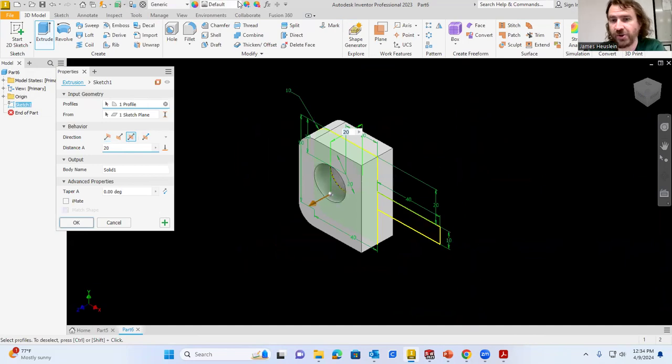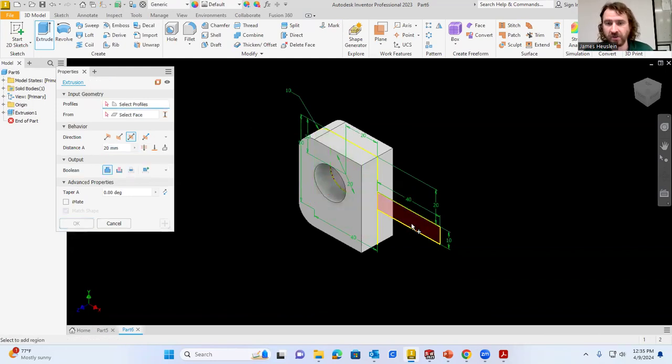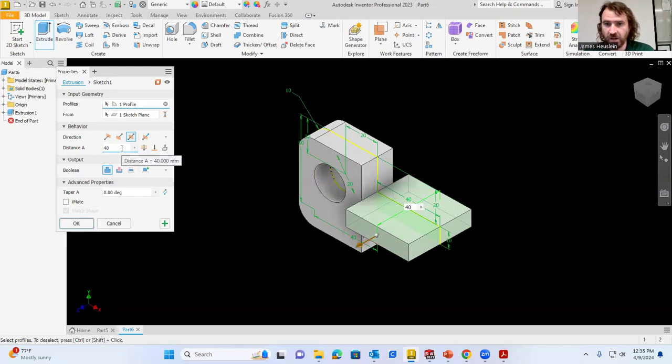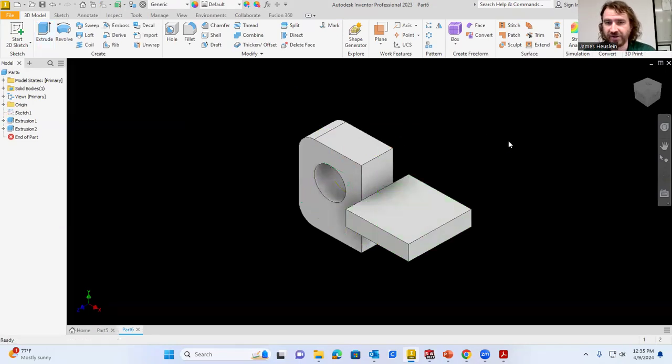And the reason being is so that this profile will be left in the middle, so we can do the same thing here and extrude this both directions, the 40 that needs to go, because that specific profile there, the rectangle here, needs to be extruded 40. So let me hit the plus sign, this, and we're extruding this 40 symmetrically, and I'll hit enter.